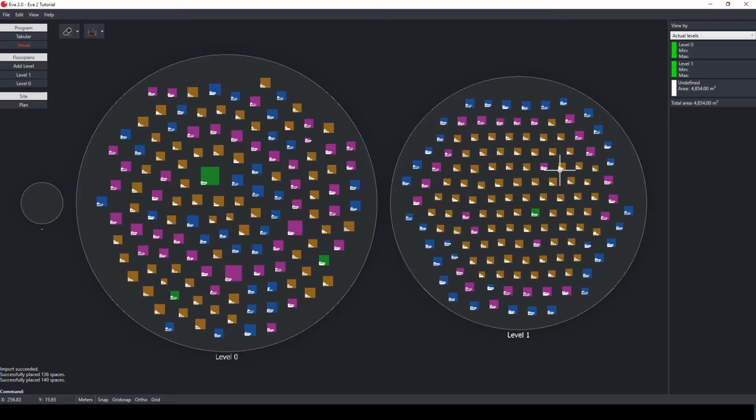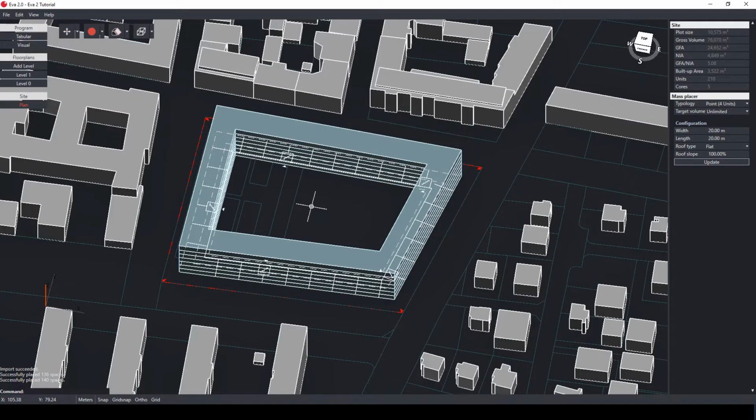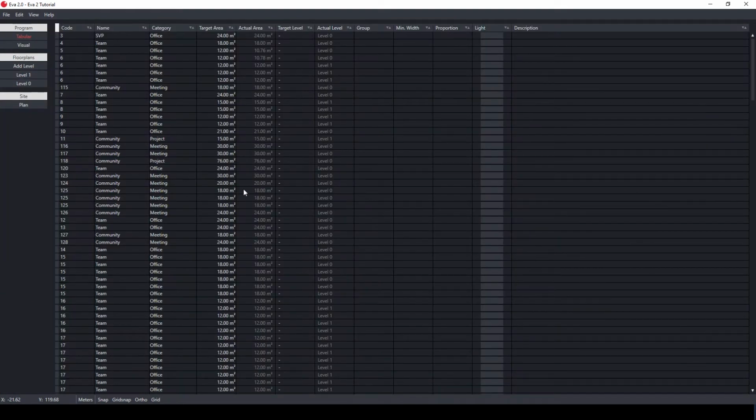We can now turn the actual levels to target levels, but here we want to choose our own outline parameter. If we go back to Plan, we find out that we can fit the room program in 2 levels in the existing building object. But because the surroundings have 4 levels, we want our building to also have 4 levels. To do so, we take a building structure outline half the size of the one before.